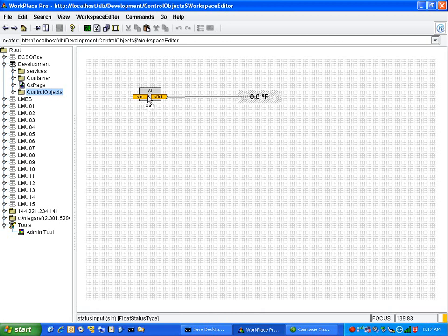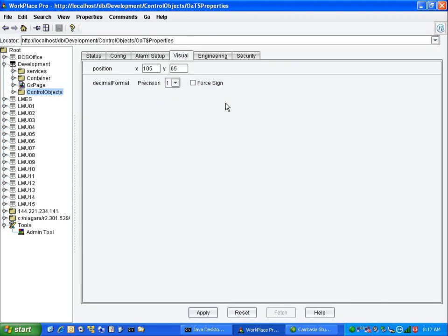The big problem with precision, and this goes all the way back to the early years of Niagara, is when you link these externally from a UNC to an enterprise server. Anytime the link goes outside of the UNC, you lose the precision and it defaults back to 2 when it lands in the destination folder. So that's kind of a pain.